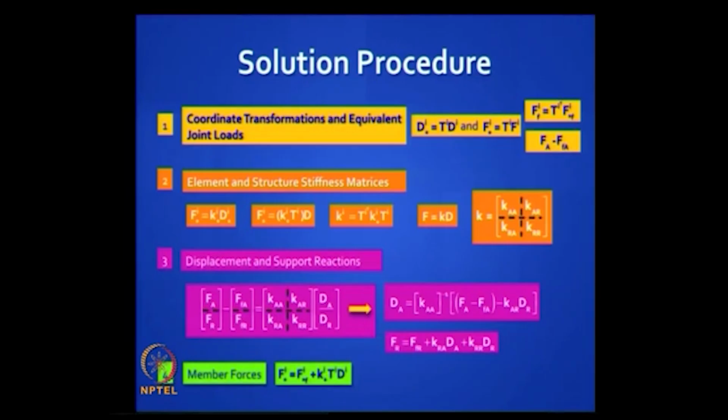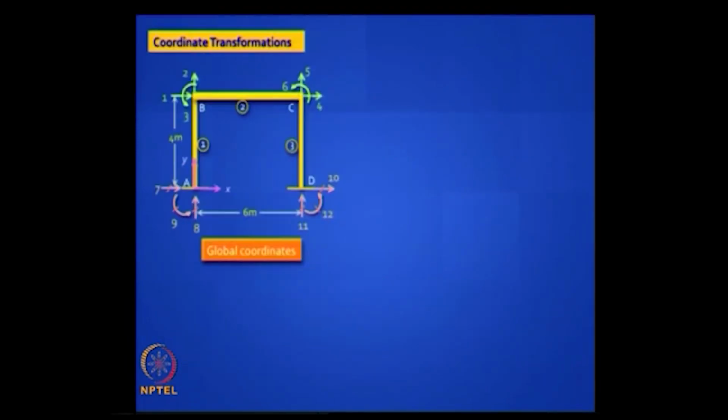So it is very familiar, and the member forces are nothing but your equivalent slope deflection equations. You have the fixed end forces and you have the additional end forces that you get from the joint displacements. Okay, so I hope now you are comfortable dealing with any problem because the procedure is well laid out. You just have to do your transformations properly. You will find the conventional stiffness method is actually very straightforward, not much thinking to do.